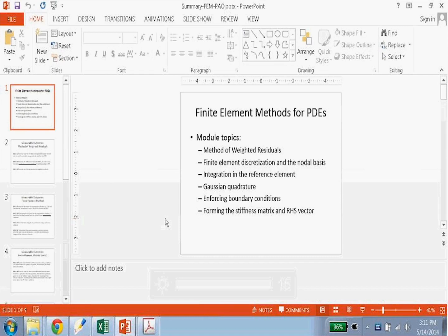So we're integrating by parts, so there's the boundary term that comes out of the integration by parts, minus now the integral where we have moved the derivative. We're going to differentiate phi_j, the one coming from the weighting for the jth weighted residual. And then our other one has been integrated, so now we just have k dT tilde/dx. And then we have the q term, which looks like an integral from minus L over 2 to L over 2 of phi_j times q dx. We don't have to do any integration by parts. This one just stays the way it is.